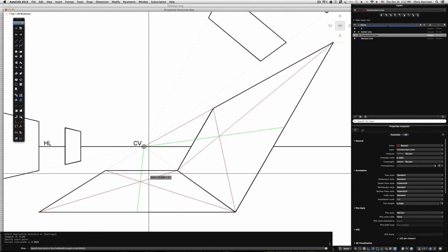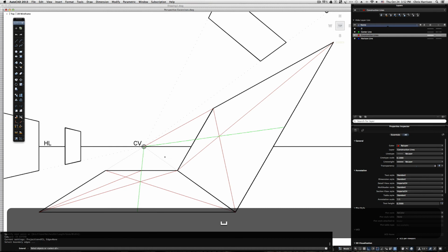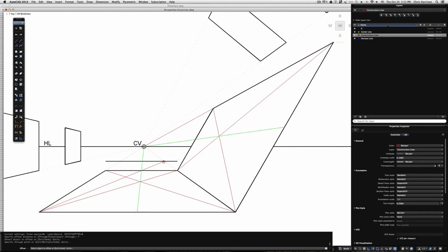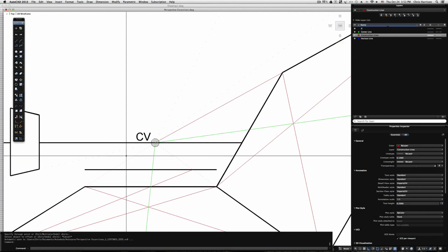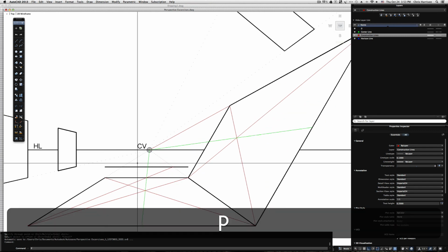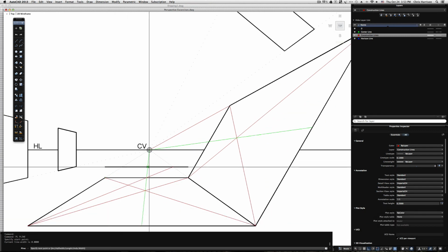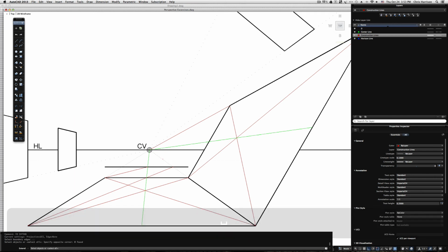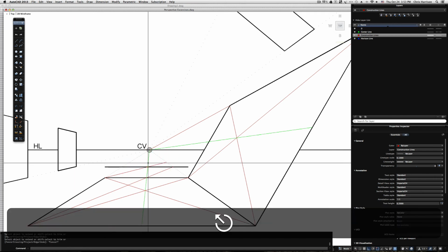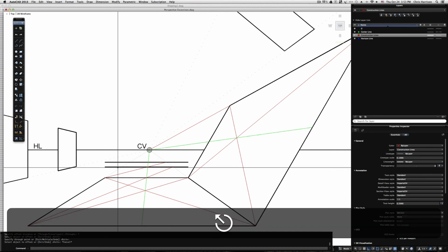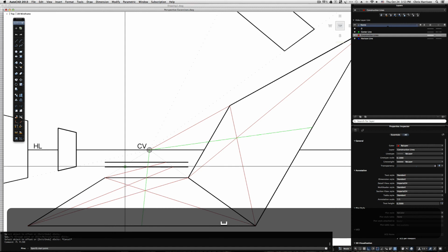Line closest towards us to the middle point, and I'm just going to extend to this dashed line here. I'm going to offset this line parallel to this line, and that'll give us the first part of the plane, and extend to the midpoint, and then extend all the way through, really. Offset. There you go. And then that'll give us that plane in depth. I'll just go ahead and match properties and clean this up.